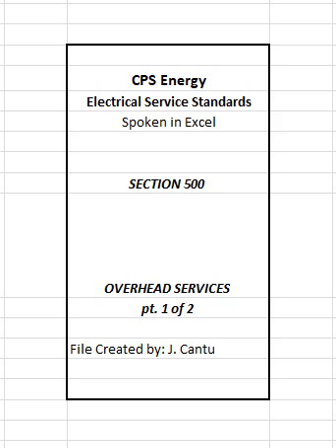505.1 Location. The point of attachment for the service drop conductors shall be located on the building service mast or other structure at the nearest practical point to CPS Energy supply pole. Exception. Clearance poles may be used to extend service drop conductor distances where approved and deemed necessary by the CPS Energy customer service representative.